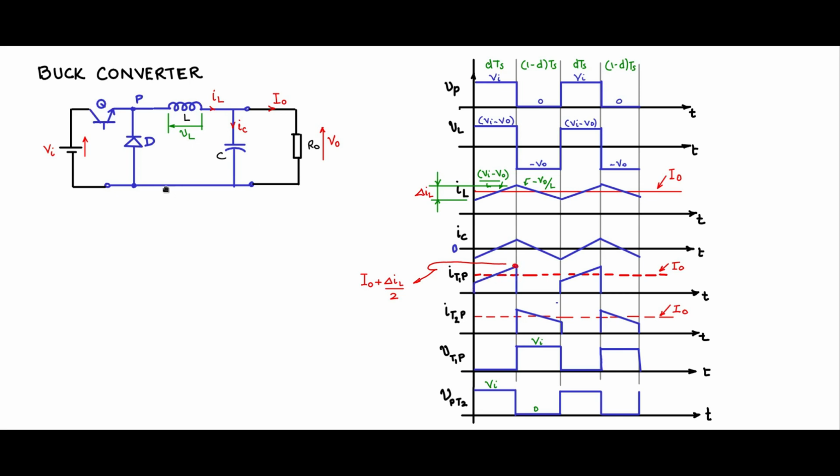When the Q is off, the voltage withstanding capability should be at least Vi. Vi comes across this. So therefore, if we take Q1, the VCEO rating for Q1 should be greater than Vi. So it should be greater than this height, and Vi max, because this is unregulated, this can swing from Vi min to Vi max. It should be able to withstand Vi max.